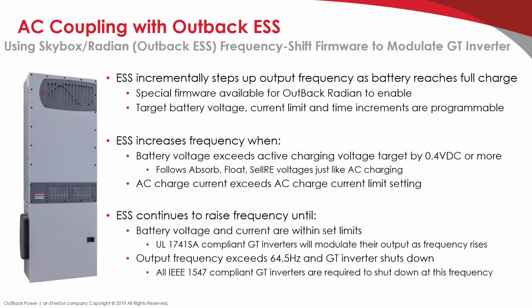I know some people have done some new installations, thinking grid tie inverters are more efficient. We'll talk a little bit more about that, but it really isn't when you're charging batteries in an AC coupling application. It's actually worse. I'll talk about that more in a moment.